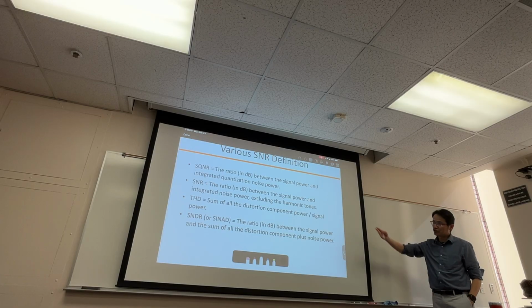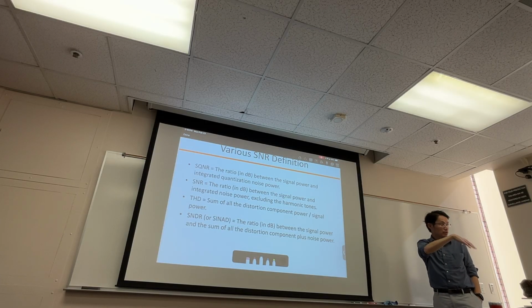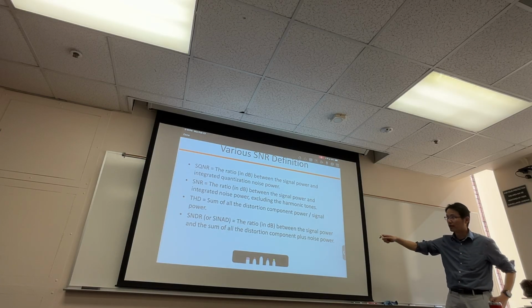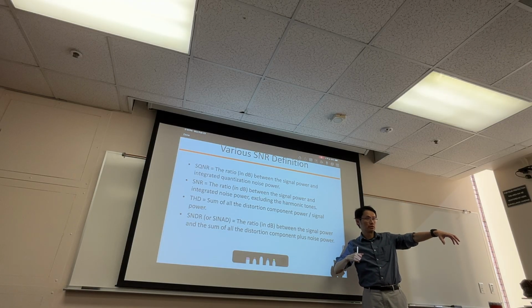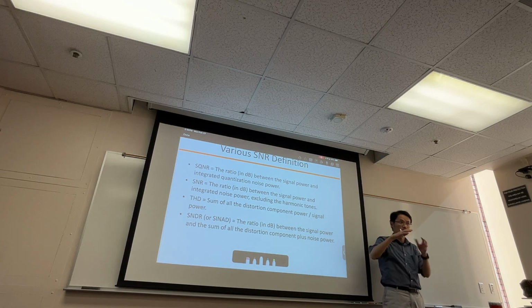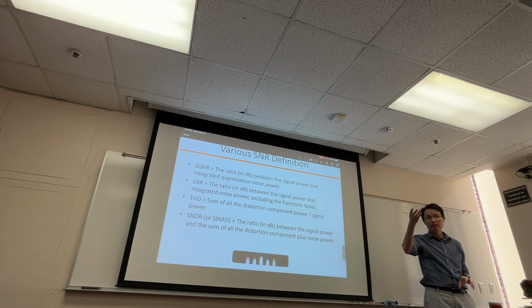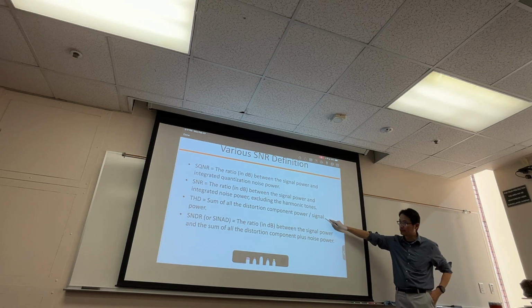Okay, THD. This part will be the same as when you design the amplifier. THD is total harmonic distortion. So basically, you sum up all the harmonic tones. That will be a negative number, right? So the tones supposedly will be smaller than your signal power.